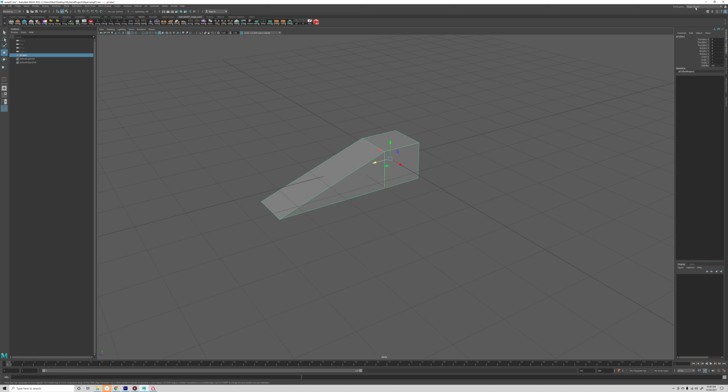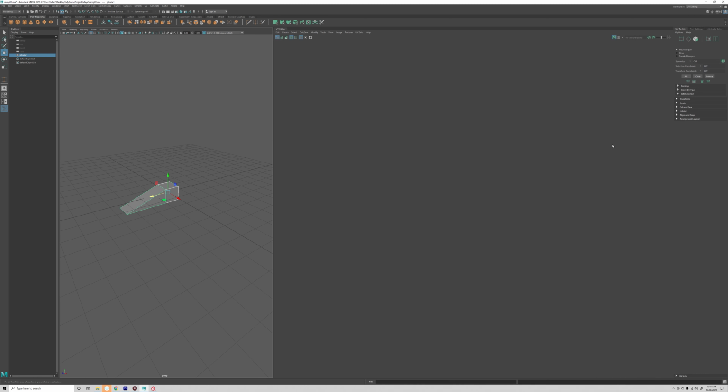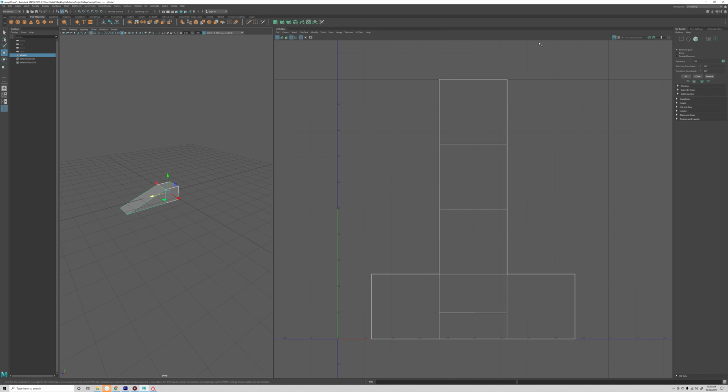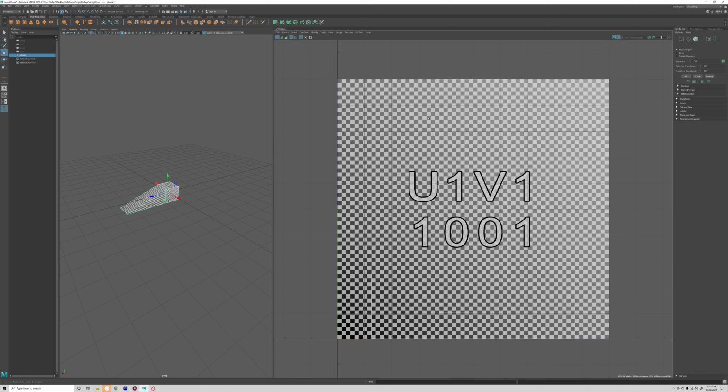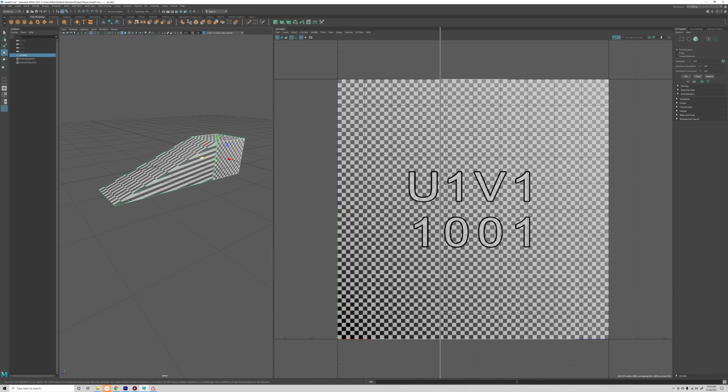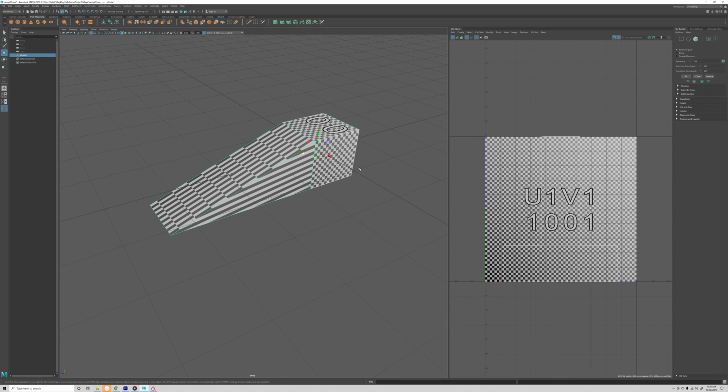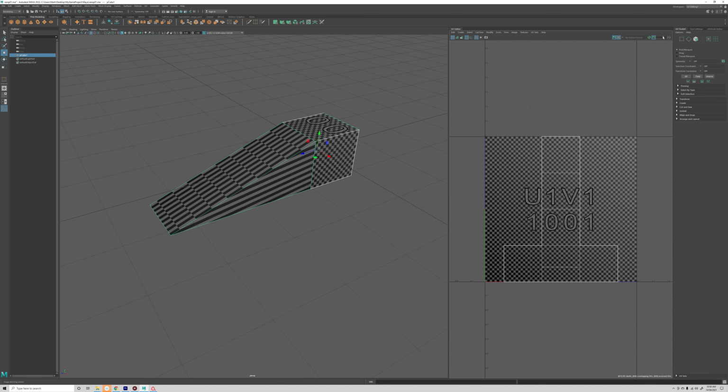I'm going to change to UV mode. So UV editing in the workspace. So this pull down menu. UV editing. Can't tell if it's a good unwrap or not because I can't see the checkers. I have to turn those on in order to see that we've got a terrible unwrap. It's very stretched. My favorite workflow for unwrapping, I'm just going to turn on this graphic. It gives me the slider. I find it much easier on the eye to see it a little darker. And it's easier to see the edges on your model.